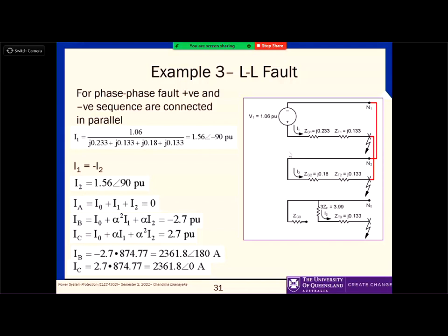So you take these 2 circuits, and once you find it, it's just a simple resistive circuit, right? Voltage divided by the addition of all those impedances. See? That part is easy. So in fault calculations, the tricky bit is forming these networks. The other part is straightforward.